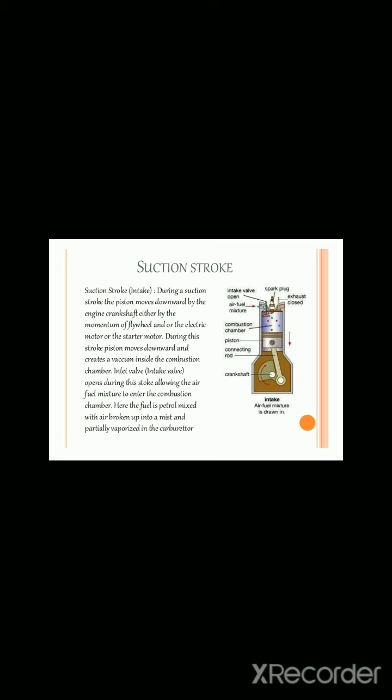The suction stroke is also called the intake stroke. During the suction stroke, the piston moves downward, driven by the engine crankshaft, either by the momentum of the flywheel or by the electric starter motor, and creates a vacuum inside the combustion chamber.